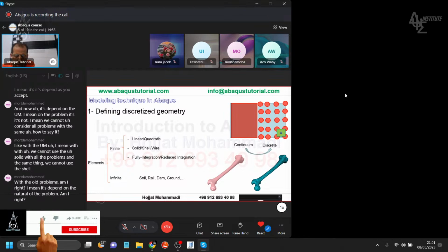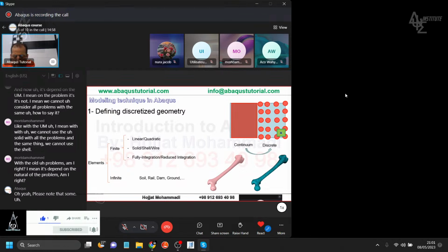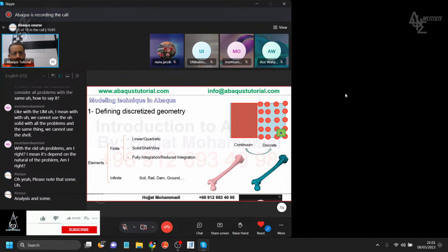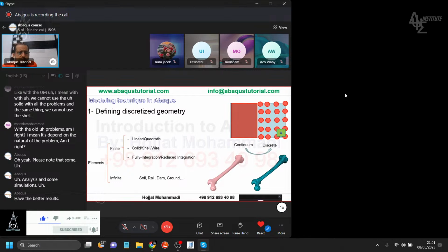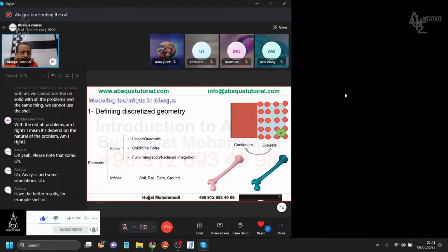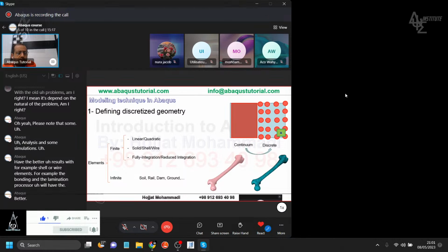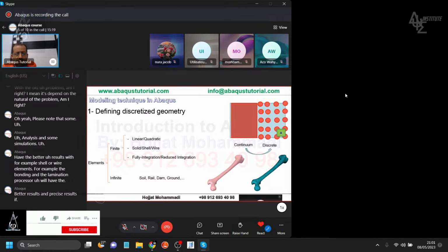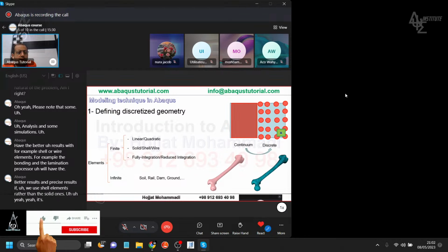Yeah, please note that some analyses and simulations have better results with, for example, shell or wire elements. For example, the bonding and lamination procedure will have better and more precise results if we use shell elements rather than solid ones. It's reasonable.